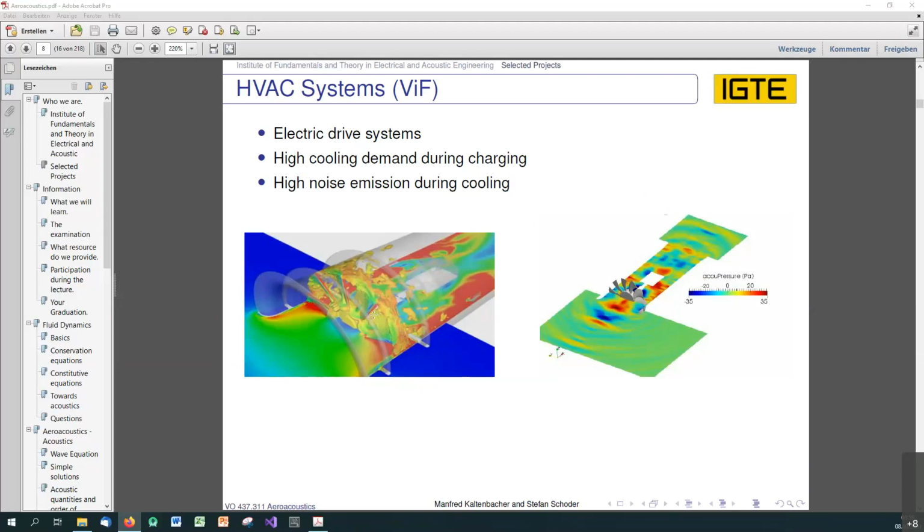which is called the blade passing frequency. And on the other side, it also makes kind of turbulent noise, which is more random and broadband over the whole frequency range. So these turbulent and vortical structures flowing through the duct and being cut by the fan are then resulting in the tonal component and also in the broadband component. Okay.